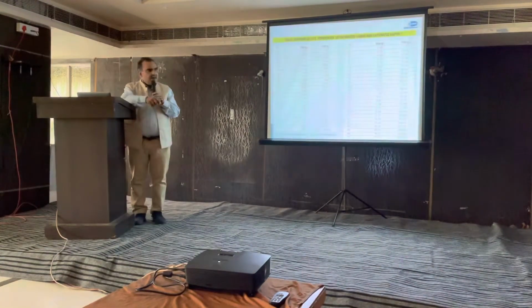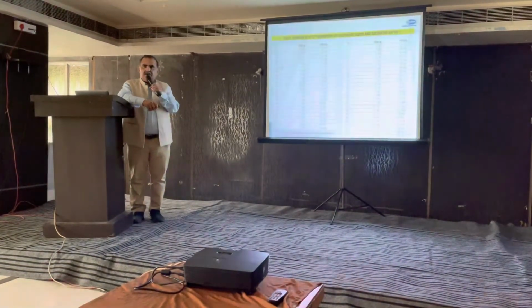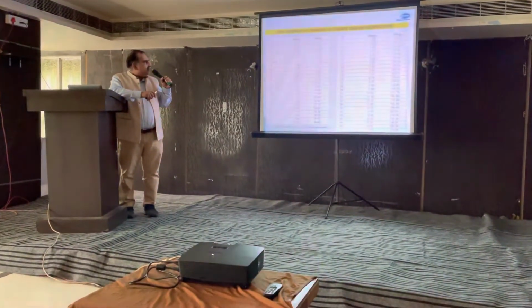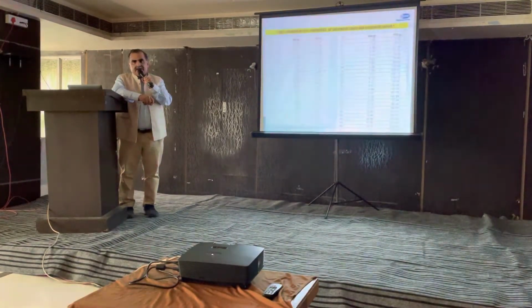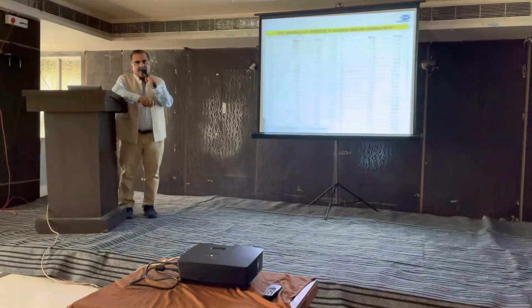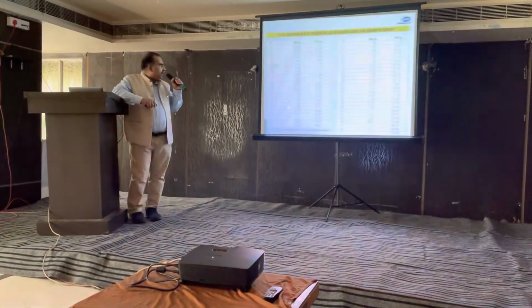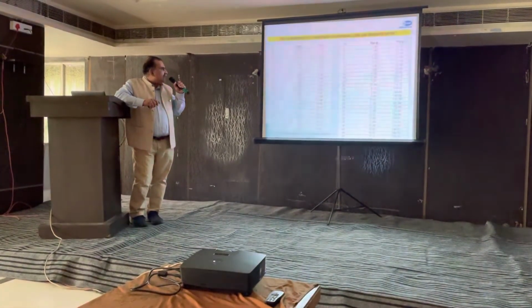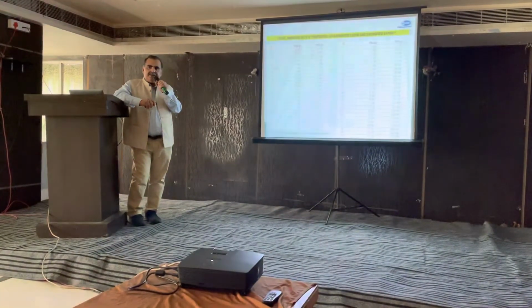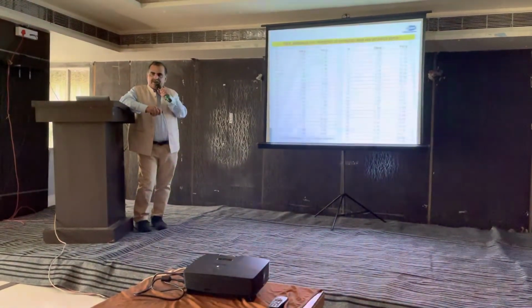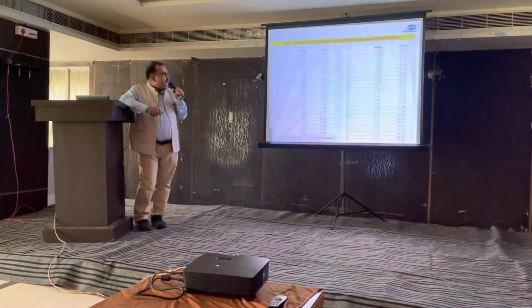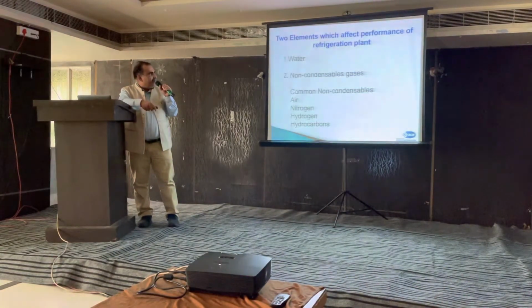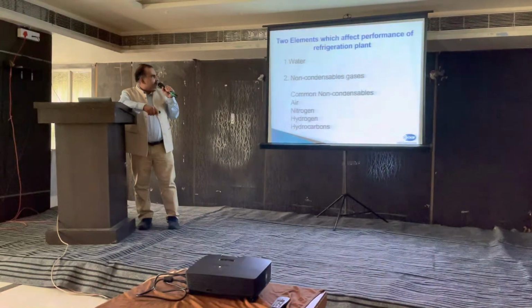The refrigeration chart which we use for all our references, Nikhil was also talking about suction pressure and discharge pressure and other things. This whole chart is related to pure ammonia, that is 99.95% pure ammonia. So when we are talking about minus 40 degrees centigrade, we are talking about minus 4 psi pressure at the suction. This is possible only if we have pure ammonia. If ammonia is not pure, then this table is not going to remain valid and our system is not going to work.